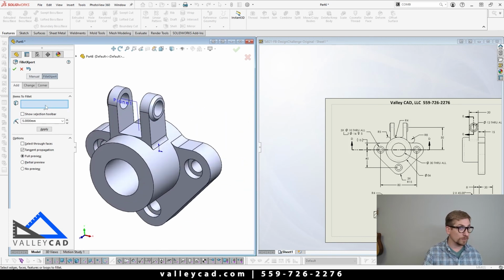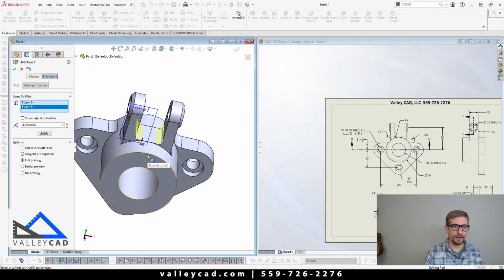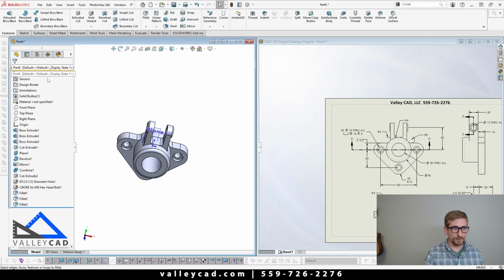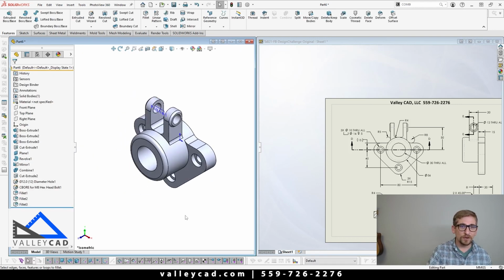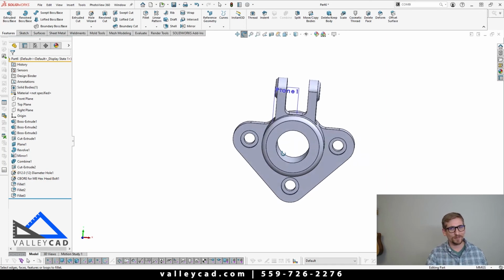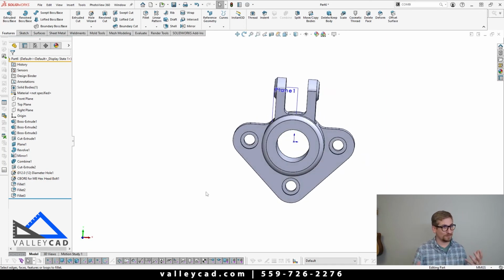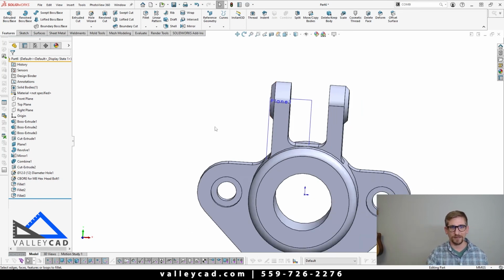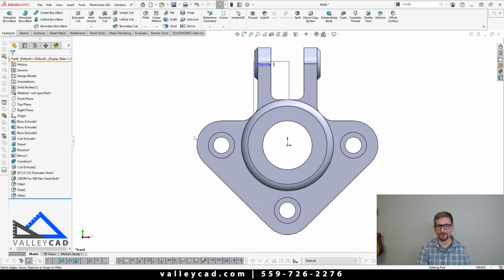Simply right click. Notice I'm still in my fillet command. Then my last one is at 4mm, and we'll click here, and then click here, and then also this top edge, and then simply right click again. And then simply get out of that command. So that actually came through and I completed our entire model. Woo! As I said, this is a little bit of a longer video, but hopefully you got something pretty nifty out of that, especially that aspect of don't merge your results and mirroring bodies about each other. That is super powerful actually.